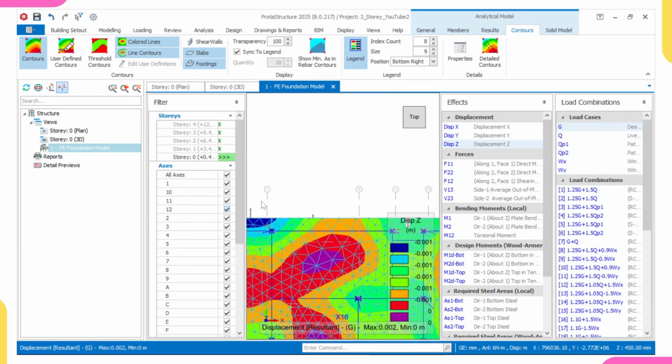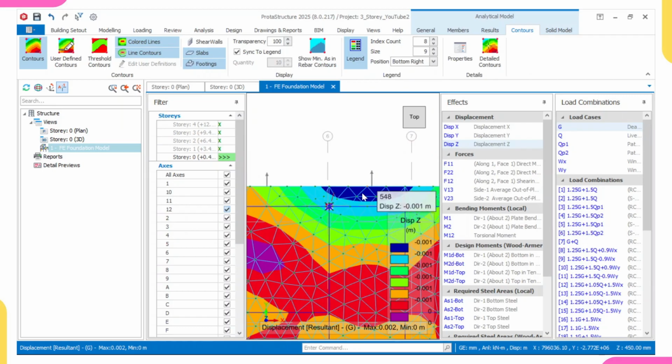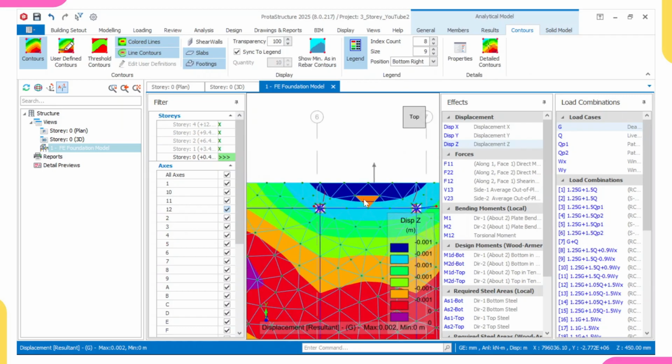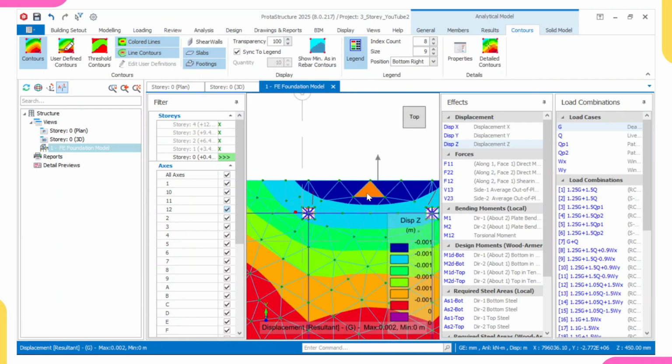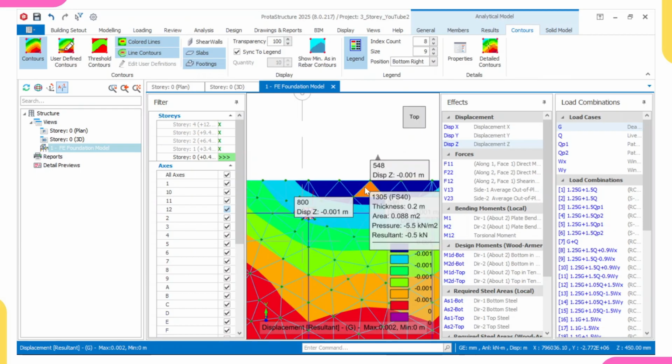Let's just design. So look at this. We're having a column here, so here is blue. It's because assuming I increased the cantilever slab, assuming I made it something like 1800, the load coming to it would be lesser, because that cantilever slab will be able to distribute its load to the soil.